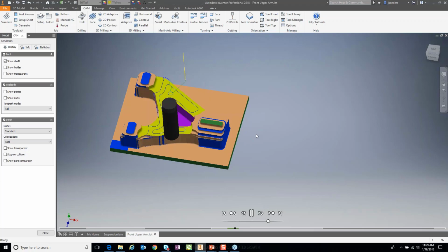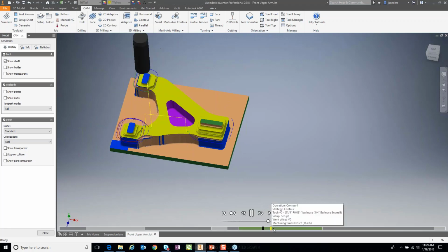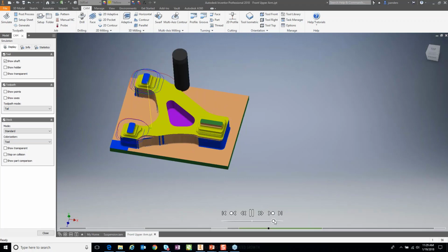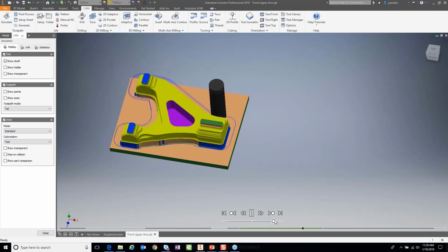See the end mill come in and clear the flat areas, and then continue on to use the cross-sectional machining, which is great for the steeper walls of the part and for removing some of the material cusps before we do the 3D contour mill work. Speed this up a bit for time purposes. Process looks pretty good. We'll have a nice finish on the walls of the part with this cross-sectional type approach.